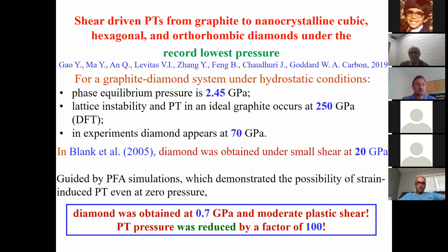Absolutely right. Plastic strain, and I believe I told you this, is a way to introduce strong defects, to introduce, let's say, dislocation pileup with a large number of defects, or disclinations, or nanograin structure. Maybe all of them contribute. Yes, this is true. So that means in general, if you want to make these high pressure phases, the challenge is introducing those defects into the starting materials.